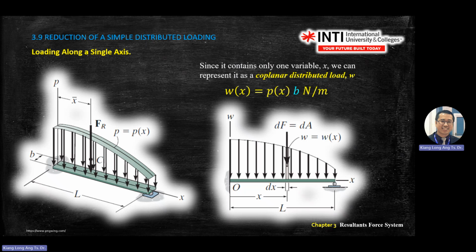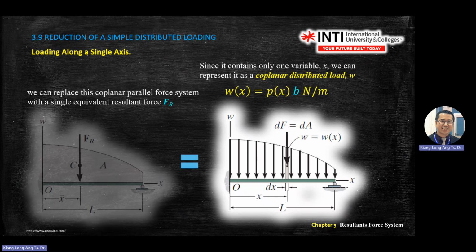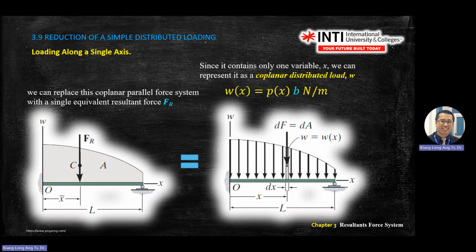Now, for example, in 2D, you're seeing this distributed load. You go to the equation there and see W equal to some multiple of X kilonewton over meter square. Change this by multiplying by the X that you have, to become a concentrated force. So you convert the one on the right to become the one on the left. When you combine all these forces into one concentrated force, there is a location for the force. Don't worry, for this location, refer to the table.